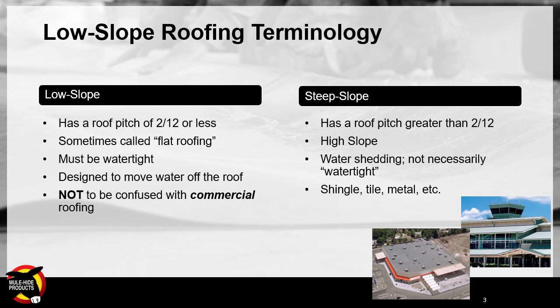What that means is, as you go across a 1 foot measurement, you have a 2-inch height or less. So a 6:12 slope would be 6 inches, and you'd have a severe angle. Low slope is completely waterproofing. That's the biggest takeaway versus shingles, which are water shedding. A lot of low slope buildings you'll see if you're catching a plane, landing at a local airport, a lot of flat buildings. And hopefully after today, you start seeing it more and more as you walk around.